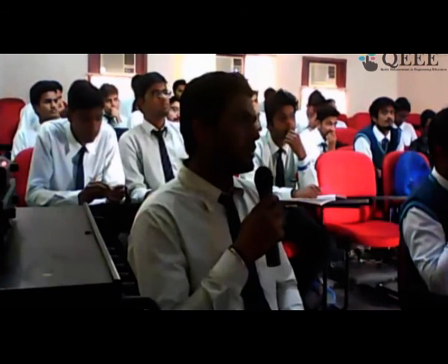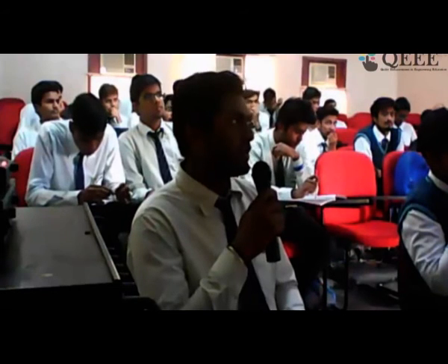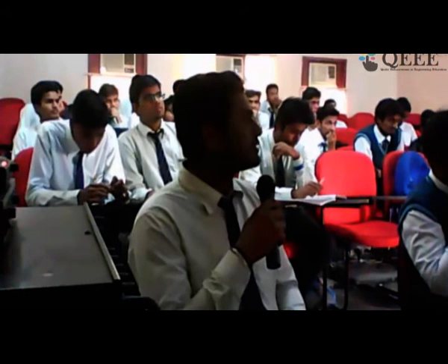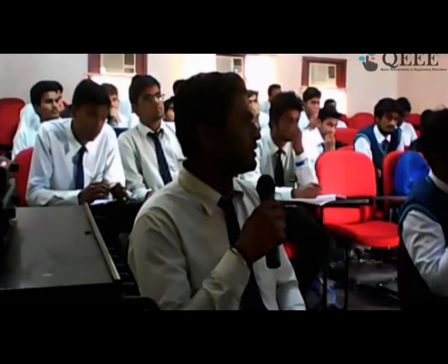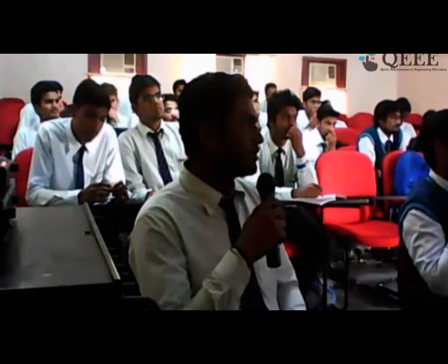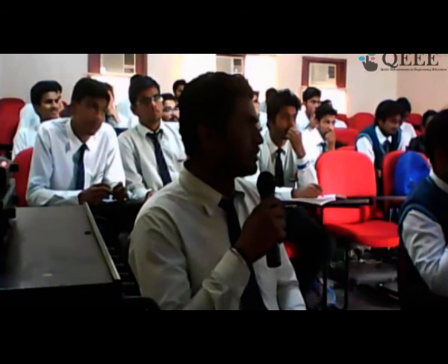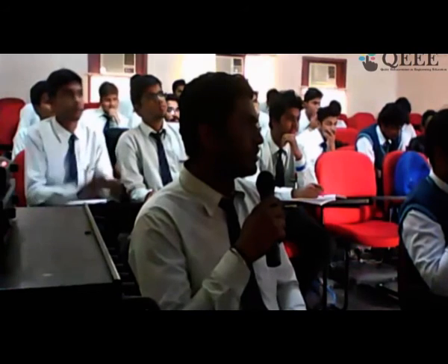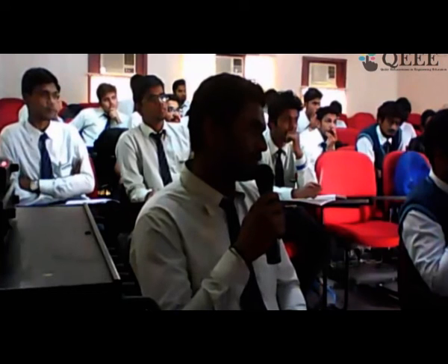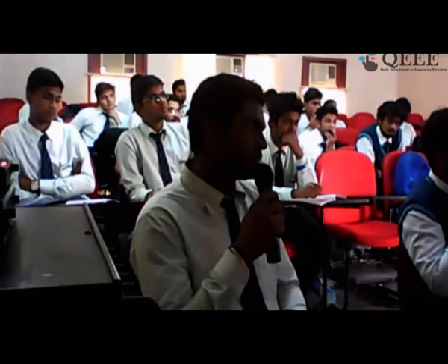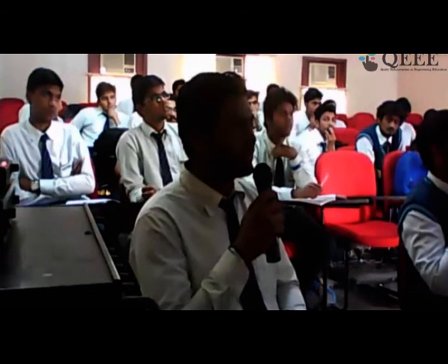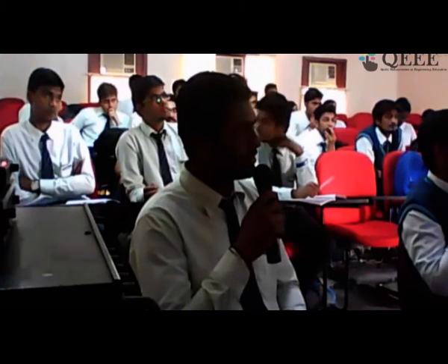Yes, next question. Sir, how can we prevent the sorptivity of the water into the concrete? To make it more compact. So this is basically because of the capillary action. If you cure the concrete better and use more mineral admixtures, you will get a more compact microstructure, so you will not have that much sorption of water. Only one way, that is by compacting we can do that. Now when I say compacting, I do not mean by vibration. I mean by modifying the mix design and ensuring that complete hydration is happening.